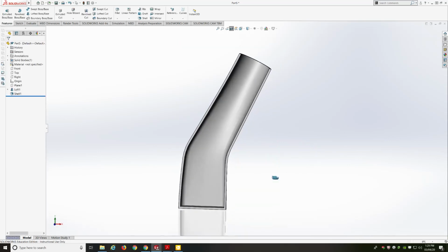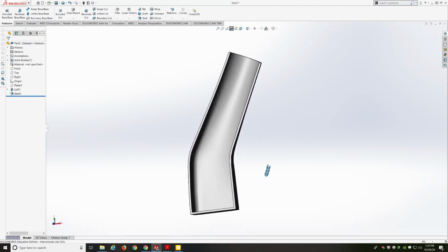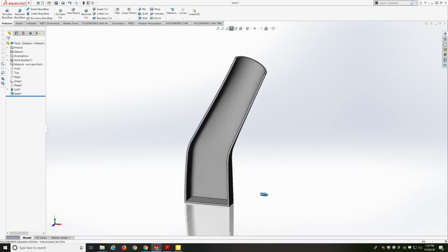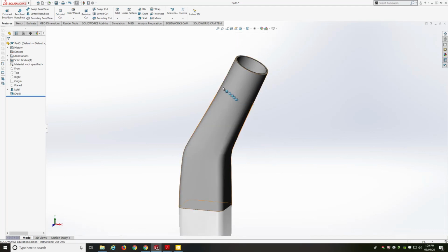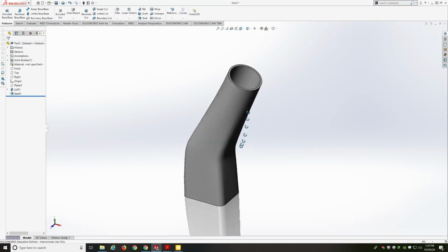Okay, and we have a 0.15 inch thick wall all the way around, including the bottom. Okay, if we wanted the shell to go all the way through, all right, let me deselect this. So I'm going to click on section view again. That shows me my natural state.